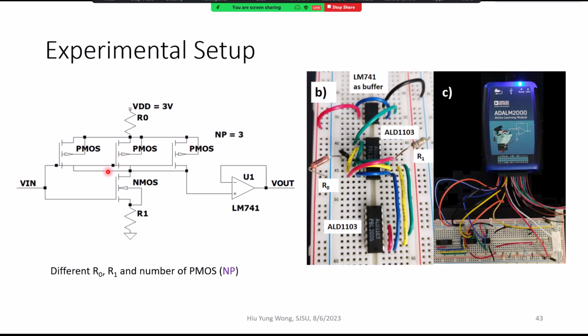And then we try to say, if you give me the measured output curve of the inverter, can you tell me what the resistance in the device is? At the same time, we add a resistor here to mimic the contact resistor. If you have a large resistor, it means your inverter is failing. This is usually what happens in semiconductor fabrication.